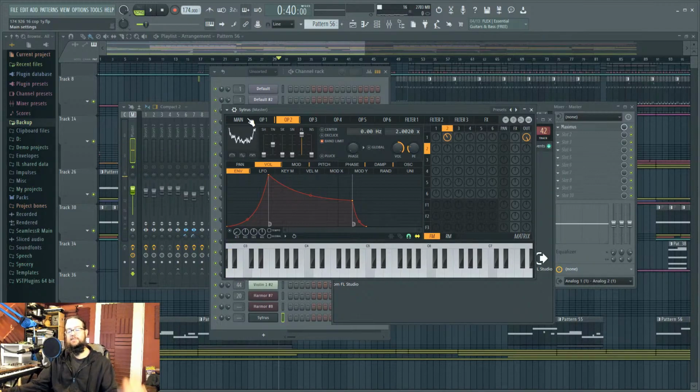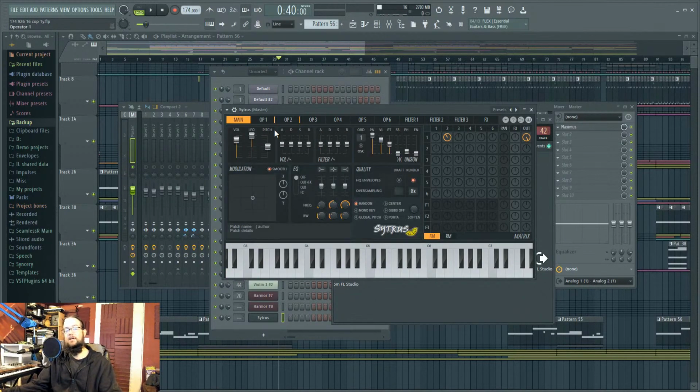Another problem we're running into is that kind of janky noise you're hearing, and that's a crap ton of aliasing. Aliasing is what happens when you generate frequencies that are higher than Nyquist. Nyquist is half of your sample rate, because that's the highest frequency that can be generated inside the math of digital synthesis. It doesn't mean that the frequencies go away, because it's not hard to generate high frequencies. A saw wave is just asking for it, and the answer is it gets wrapped around. As high as it would have gone above Nyquist, it comes back down below Nyquist.